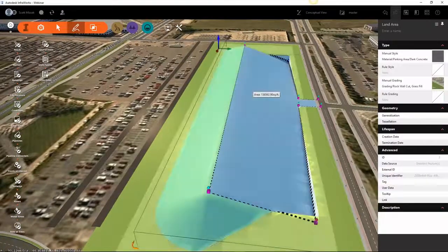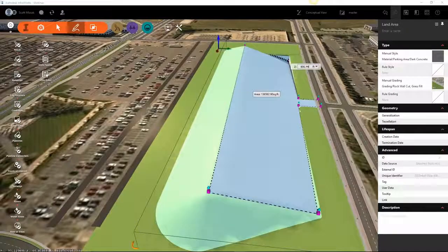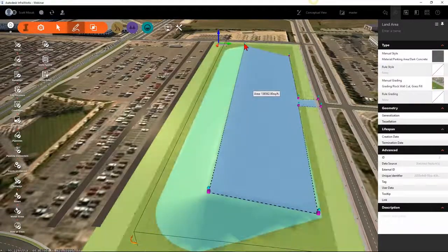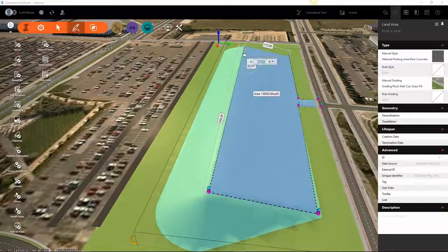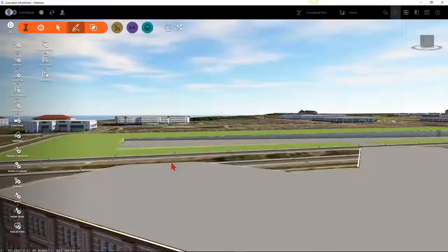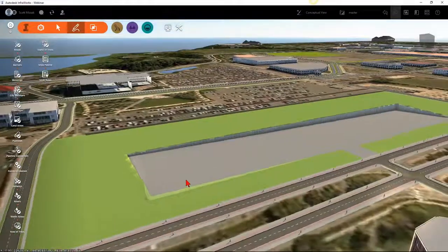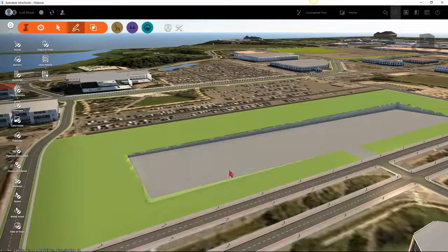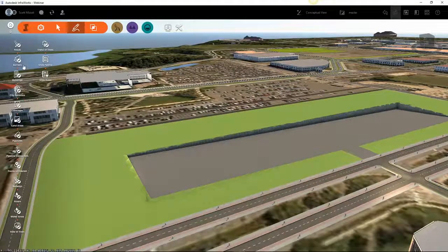So, doing silly things, I actually went the wrong way, and I should have had the bring that back in so I daylight normal, but now on the back end, I'll have the cut situation. So it recognized cut to fill, fill to cut, and it automatically made that transition. So let me take a quick peek at that grading.